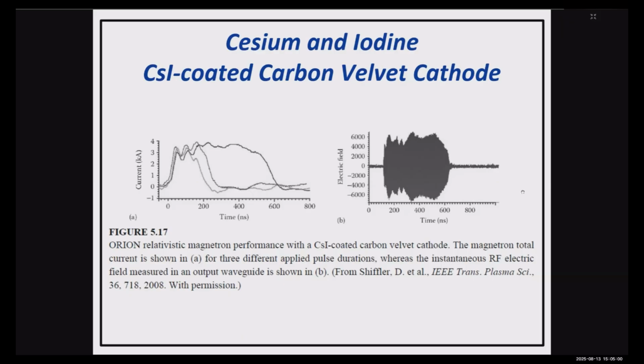Sir, pulse shortening is when plasma is conductive, so then it stops the pulse formation. Is it right when plasma is formed on the cathode? Yes, when the plasma forms on the cathode and expands and closes the anode-cathode gap. Yes, this is the short circuit.